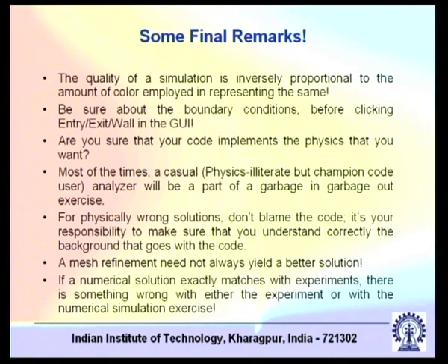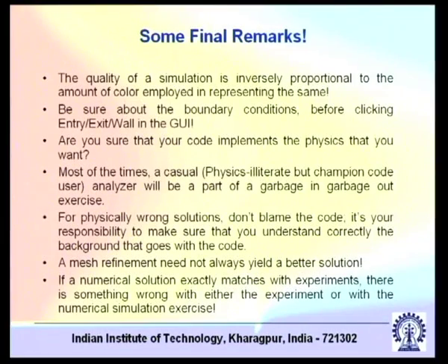A CFD code fundamentally is what? A CFD code fundamentally is a PDE solver. So it's a coupled PDE solver, so to say. So if the PDEs can be cast in a general conservative form, then only is your CFD code possible to be implemented for the particular problem that you are implementing. If you have equations which do not fall into that category, simply do not use that code. Try to use a different code or develop a code or whatever, but do not use it.